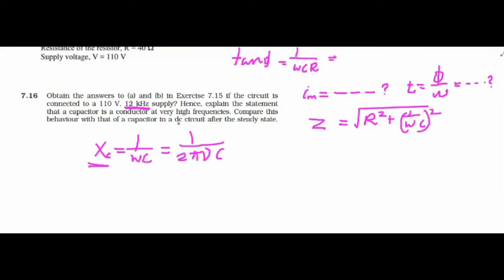While in the case of DC, as you have already seen when we discussed the theory, the capacitor has infinite opposition against DC, so the capacitor will block DC. Due to the increase in frequency, its reactance decreases. So in the case of AC, it can very easily pass through the capacitor. That is the result you will obtain from the value of Z.